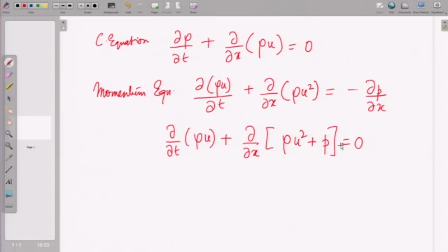So, we would like to have them in the conservative form where we handle fluxes, and though there could be discontinuities in certain derivatives like say velocity derivative across such discontinuities, but the fluxes will not jump.